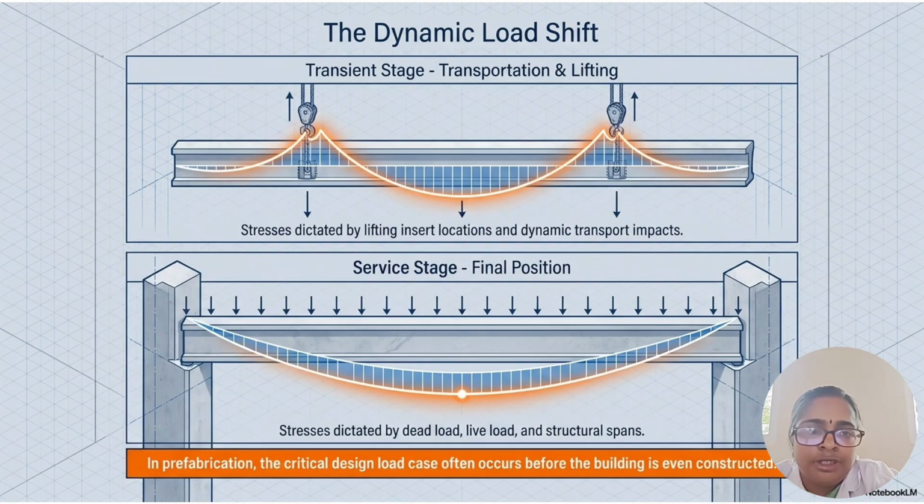And this image gives you information about the live and dead load shift from the transient stage to the service stage. In prefabrication, the critical design load case often occurs before the building is even constructed.